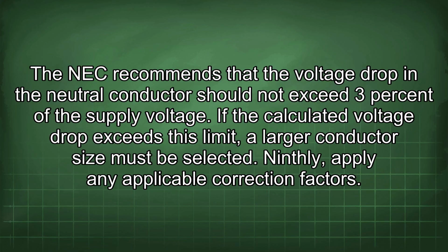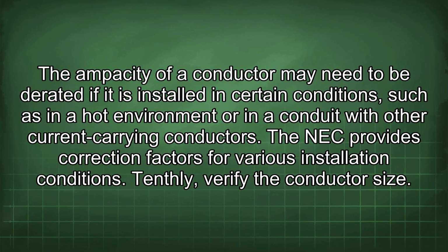Ninthly, apply any applicable correction factors. The ampacity of a conductor may need to be derated if it is installed in certain conditions, such as in a hot environment or in a conduit with other current-carrying conductors. The NEC provides correction factors for various installation conditions.